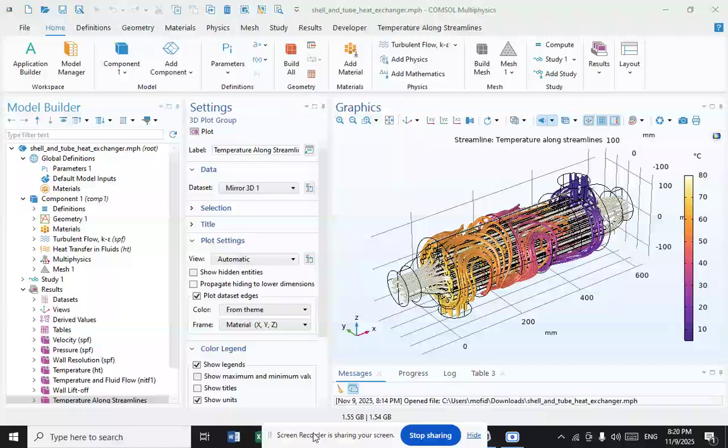The countercurrent design is the most efficient in that it can transfer the most heat from the heat transfer medium per unit mass due to the fact that the average temperature difference along any unit length is higher. In a cross-flow heat exchanger, the fluids travel roughly perpendicular to one another through the exchanger.